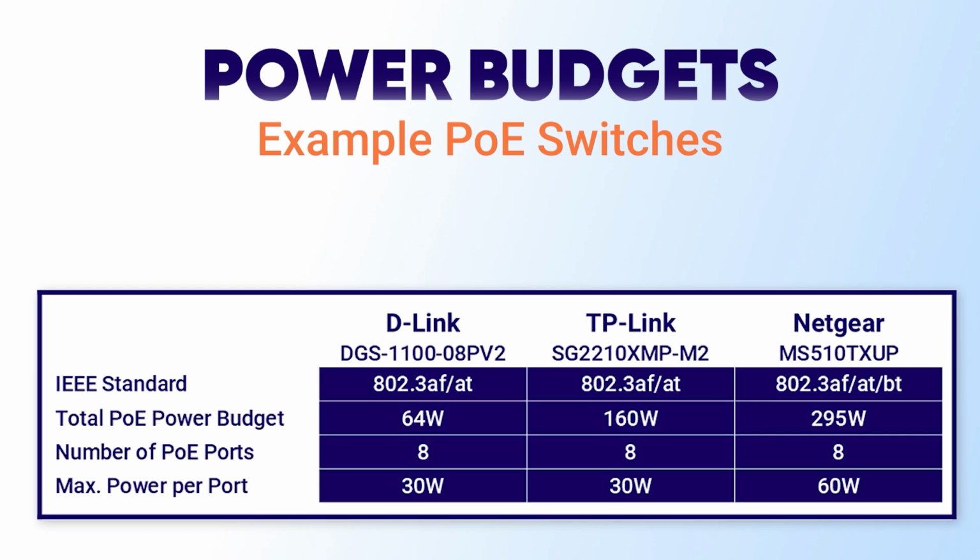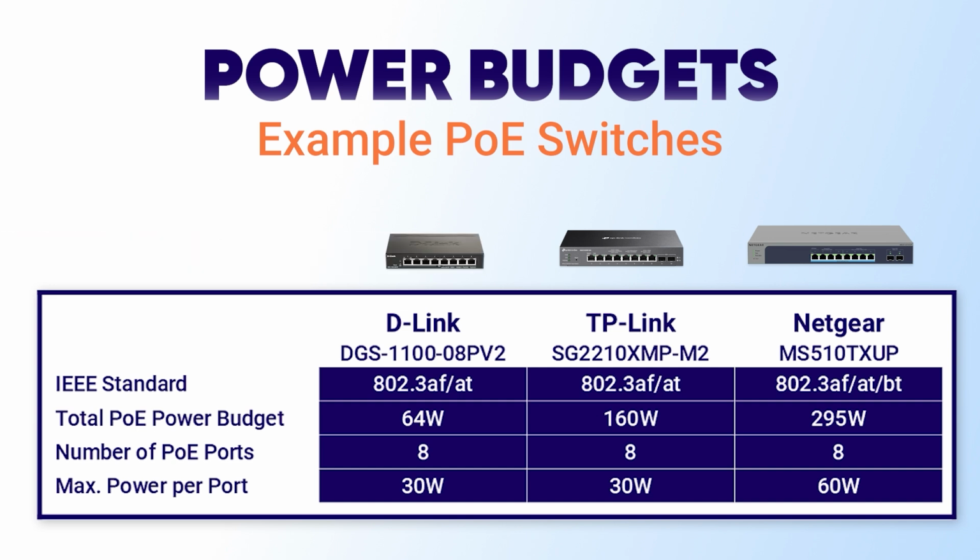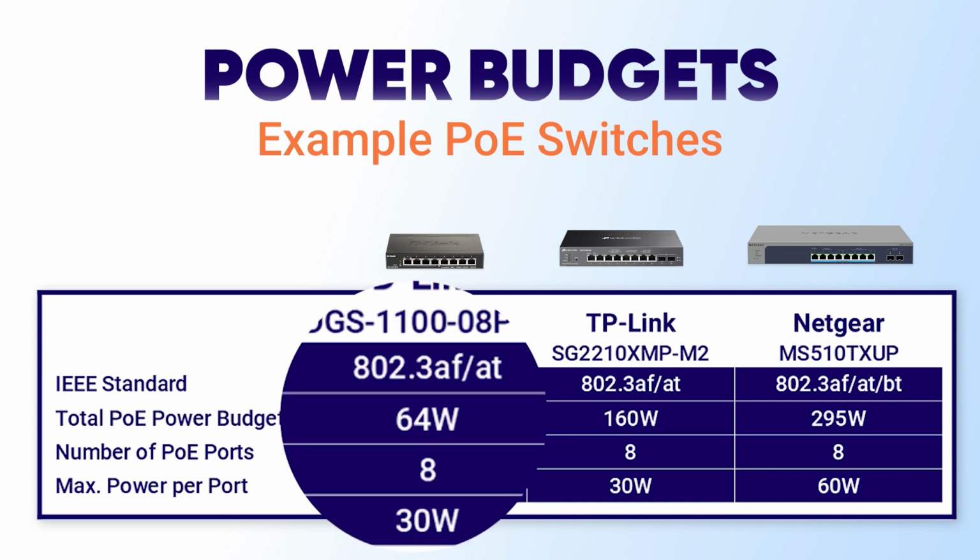Here are some examples of different PoE switches from different manufacturers. All 3 switches support 8 PoE ports, but they are very different in terms of features and functionality. The first switch, with a 64-watt PoE budget, could support 8 Class 2 devices across all 8 ports, but could only support 2 Class 4 devices.